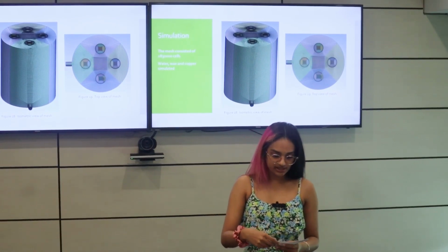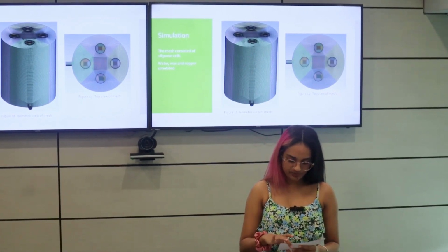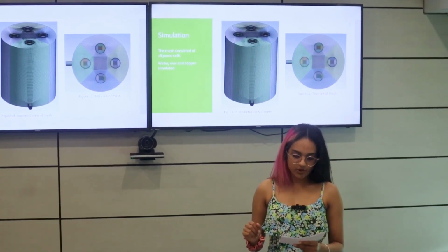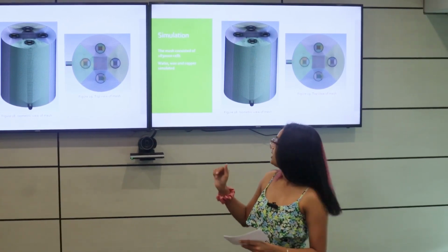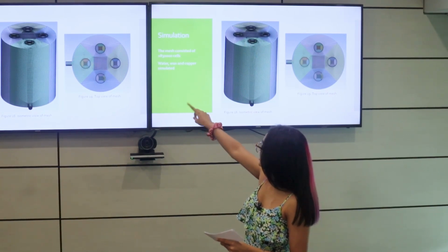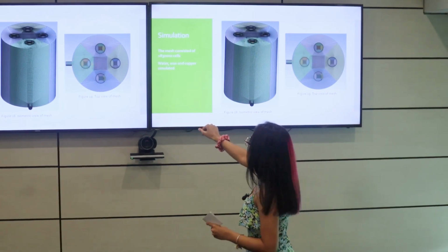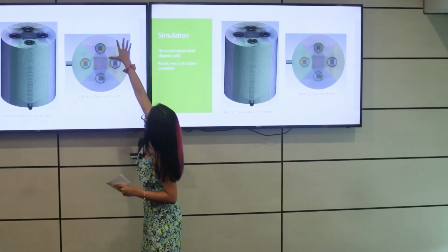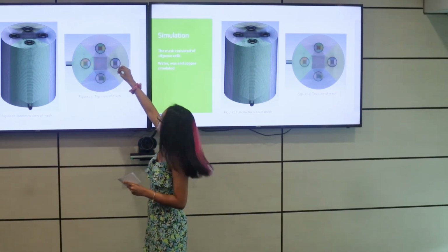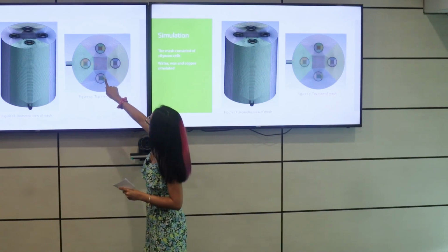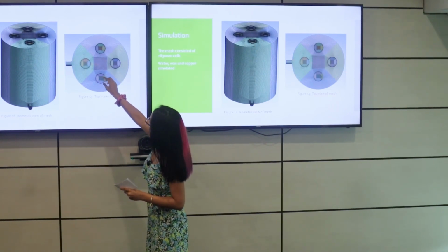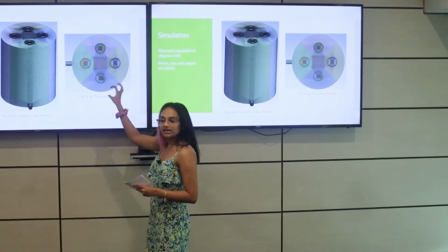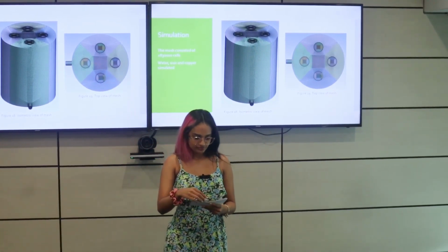My mesh can be seen here in figures 18 and 19. In order to get a mostly consistent mesh, I broke up my area into the regions that you can see here in the different colors. So these different colors are not different materials. These bigger blocks are one material, but I broke it up for meshing, and the same with these tubes. So the square and these regions around it, it's just the phase change material, but I broke it up in order to get a more consistent mesh.